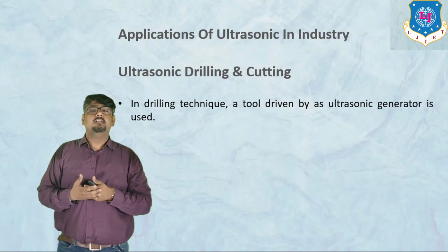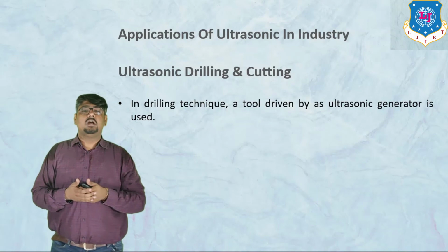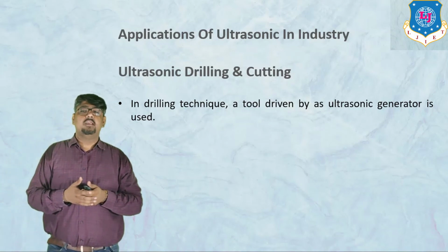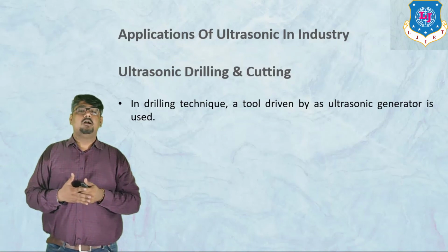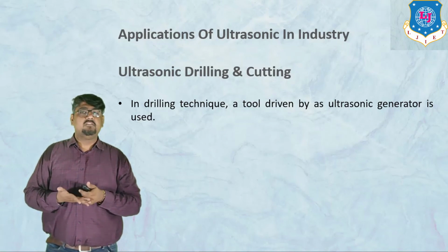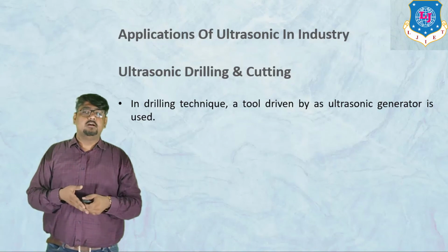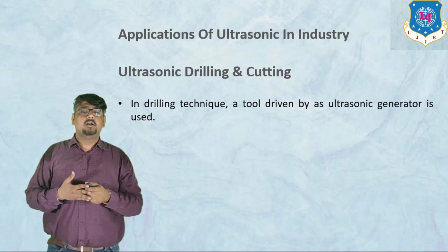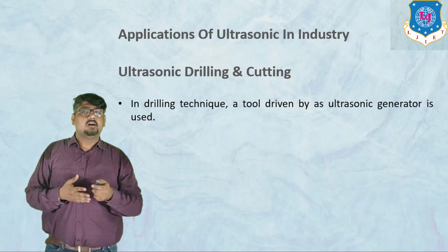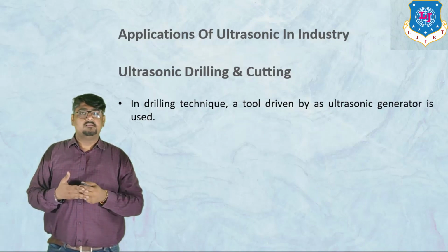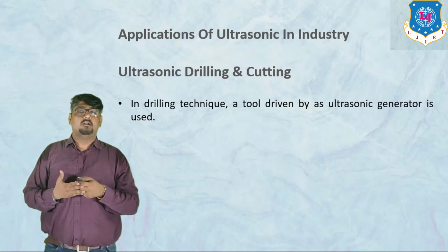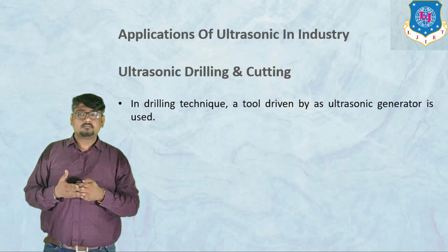An abrasive is a material that is used to sharpen or finish a sample by rubbing, which leads to a part of the sample being thrown away. That is the definition of abrasives. So here we are going to use abrasives such as boron carbide or silicon carbide. Carbides are very hard materials, so they are used here for cutting metals.